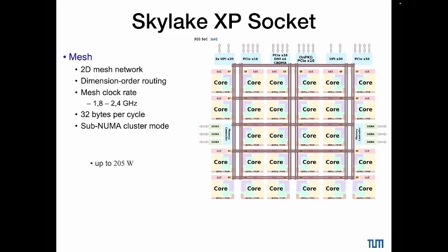So cache coherency means if you have caches in the processors and the processors work on the same addresses, then they have copies of the address and these have to be kept consistent, right? So if one processor writes the address, the other processor needs to be informed that there is a new value there, okay? And in such a network, it's implemented that you actually have a sort of directory. The directory tells the processor, oh, there is a copy, and this has to be updated, right?